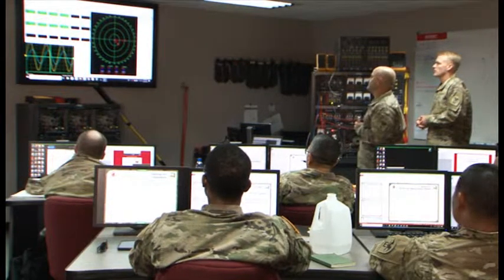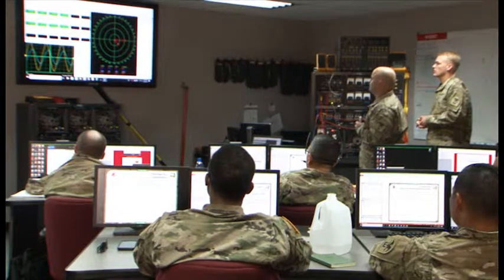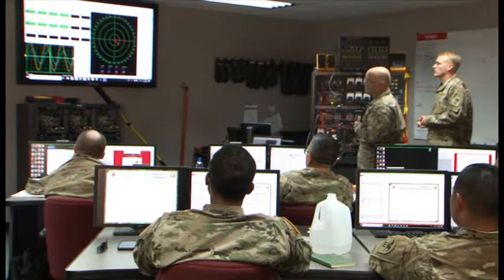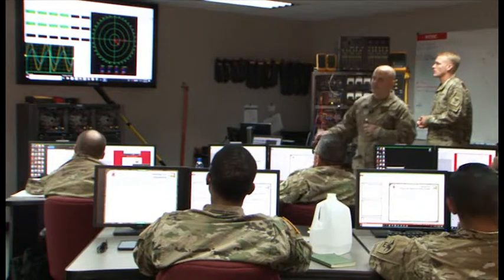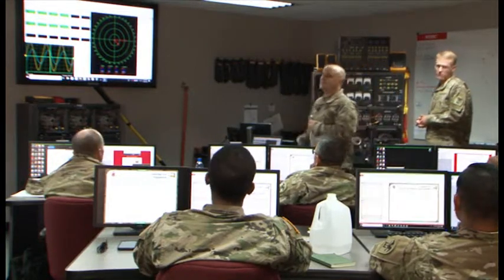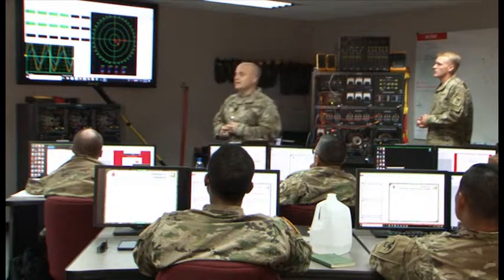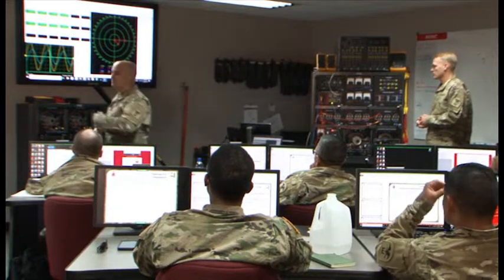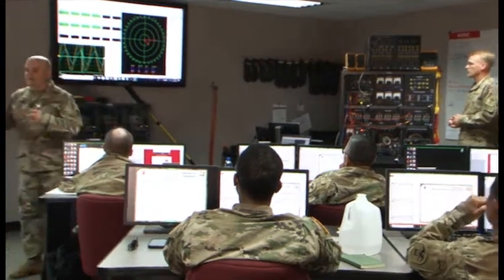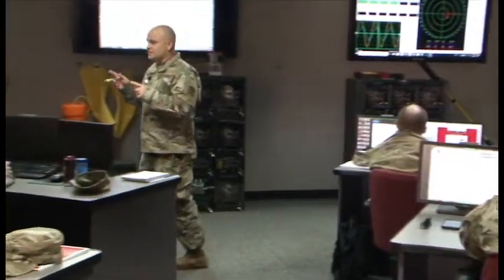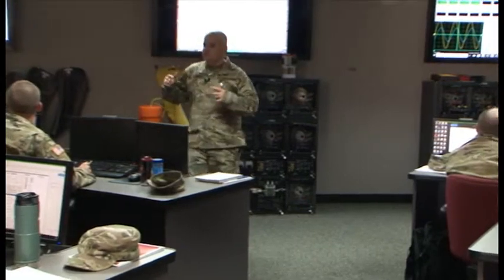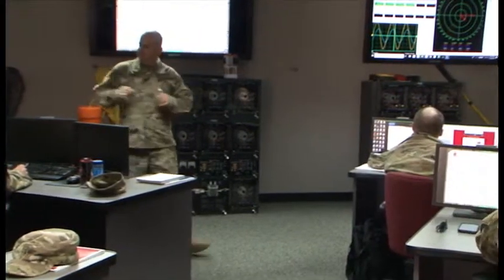So my I sub S here is a result of two different currents going through that circuit, right? We got the current going through the branch that has a resistor and the current going through the branch that has the inductor, right? And just like we showed with that voltage problem before, the mathematical sums of those didn't come out perfectly to what the source was, like we did with Kirchhoff's voltage law, because we have different angles, okay?